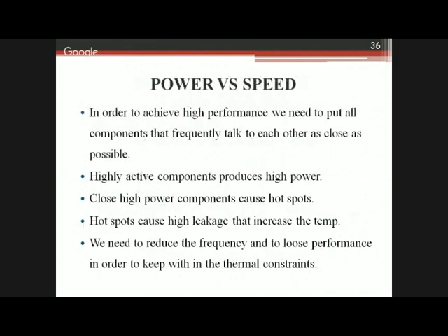This is another trade-off between power versus speed, which we have to take care of. In order to achieve high performance, we need to put all the components that frequently talk to each other as close as possible. This is important from the design point of view. Those components which intensively transmit or receive data from each other, we have to place as close as possible.